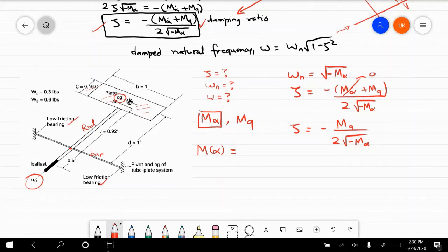So the moment as a function of angle of attack is equal to negative times this L times the change in lift. And we know it is negative because an upward lift is going to try to turn this nose downward, right? So that's why we put a negative. But I said this is a function of alpha, and there is no alpha here. You should understand that the dependence on alpha is inside this delta lift. Okay, so this is equal to minus L.